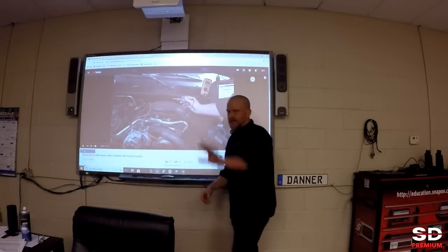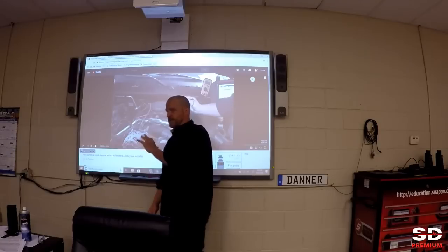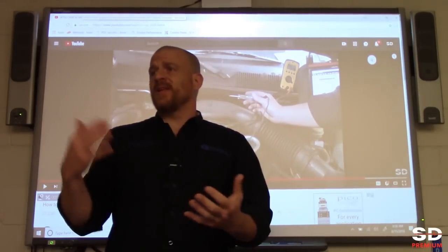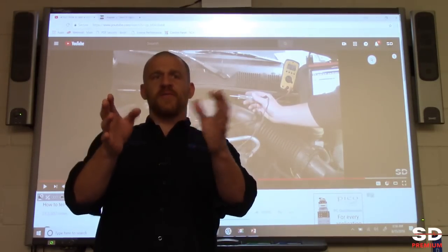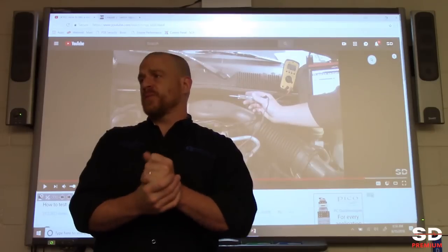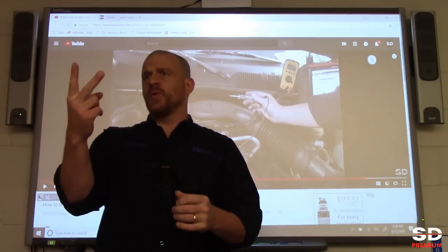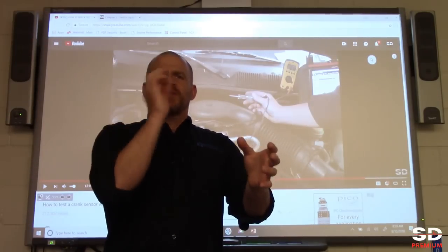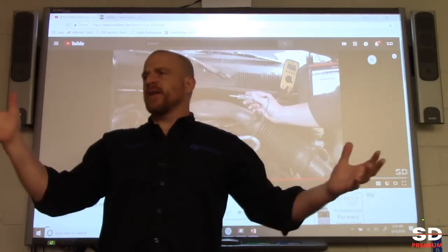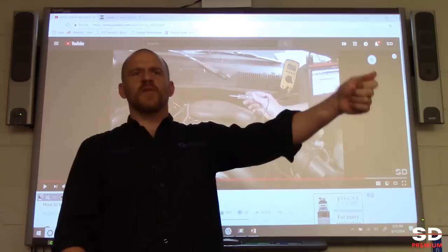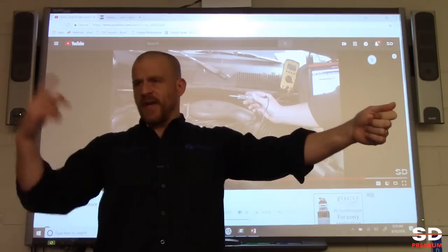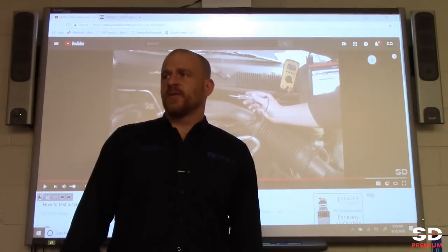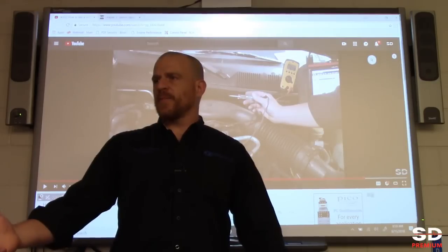All right, let's watch this bypass test. The lead into this, so we don't have to watch it here. You can watch it yourselves later. On this particular car, we need both cam and crank signals simultaneously for me to get an RPM signal on the scan tool. I need 2. So to do the bypass test, I have the crank sensor unplugged, and I show the test light on and off the signal wire first, and I don't get an RPM signal. But when I crank it over and now provide the computer with a cam signal, while I'm triggering the crank, I can make the computer show me an RPM. Okay, that's what we're about to do.